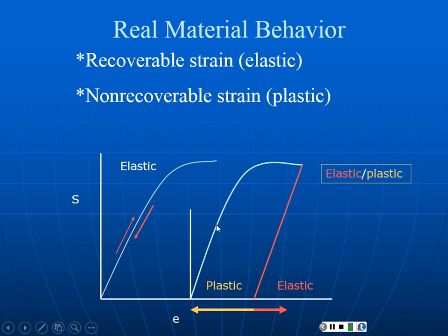However, we can also have, with nonlinearity, when we unload, so this would be loading up to some high load, stopping the test, and unloading. We recover elastic strain, that is, the part relaxes, and we recover the elastic strain, but the strain does not go back to 0, even though the stress is now 0 at this point. This is plastic or permanent deformation. Okay? Now, that's all plastic means for us right now: non-recoverable. And elastic simply means the strain recovers if you take away the stress.